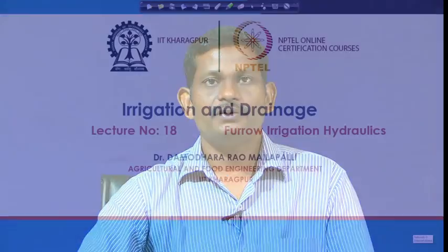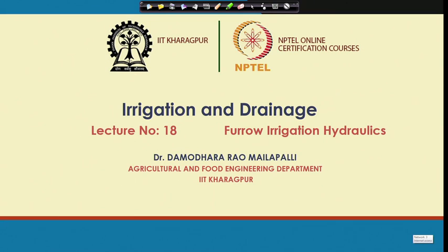Yes. So, in lecture number 18, we are going to focus on the furrow irrigation hydraulics again. Previously, by knowing the advance curve, we were able to estimate the infiltration characteristics, like the Kostiakov infiltration parameters for a particular field soil. But in this lecture, we are going to see the whole procedure to find out the advance curve by knowing the infiltration parameters.